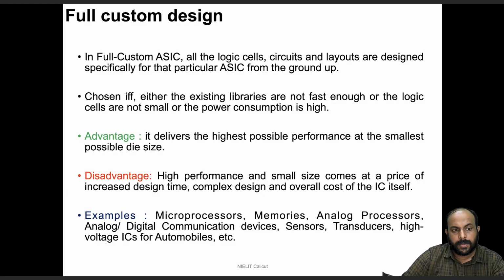This particular technology or full custom design is very complicated, and it is chosen if and only if the existing libraries or macros, or the logic cells, are not enough to meet a particular power consumption. If the power consumption of the already available commercial off-the-shelf libraries is too high to meet the target power, which should be low in our particular product, we design everything from scratch, including the circuits, the layouts, the logic cells, etc.